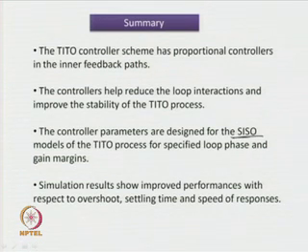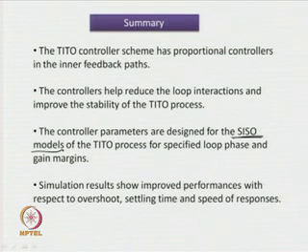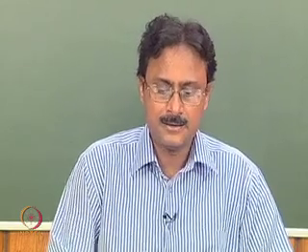Basically, the design technique available for SISO models has been employed to design controllers for the TITO process, and simulation results of course show us improved performances with respect to overshoot, settling time and speed of response. Although a comparison has not been given, often it is found that the PID-P controller results in satisfactory performances compared to PID controllers alone in the loops.